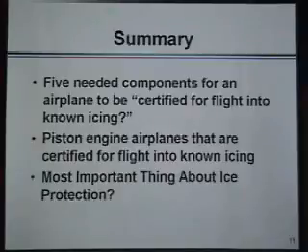So number 4 is dual, or at least 2 separate, pitot-static systems. And then the number 5 thing is you need an ice protection system for the pilot's windshield. You need pilot windshield ice protection, so that if you happen to fly through icing conditions, you'll still be able to see out the window. Not in flight, not during cruise, but certainly when you come in to land, it would be really nice to be able to see the runway prior to touchdown.